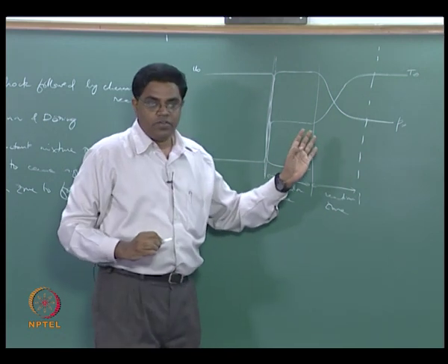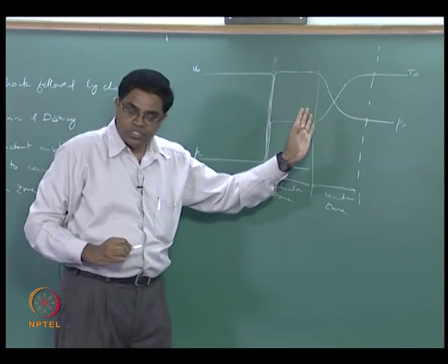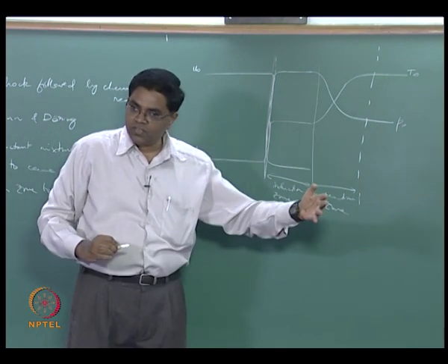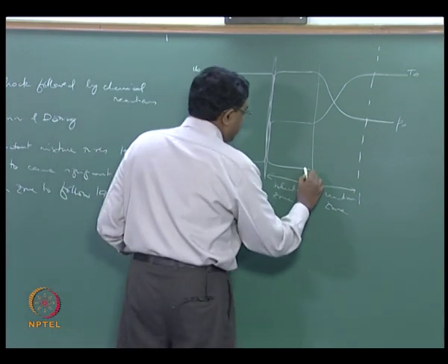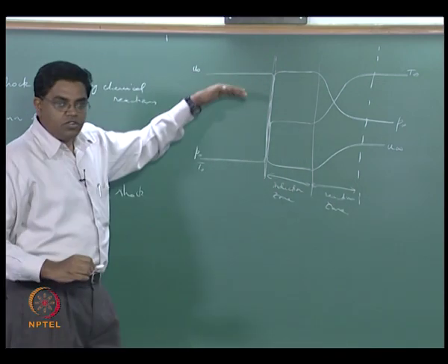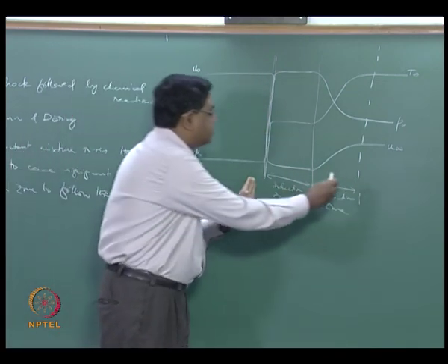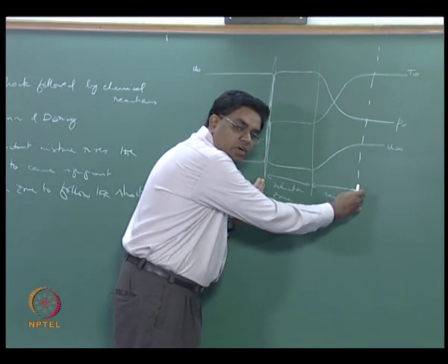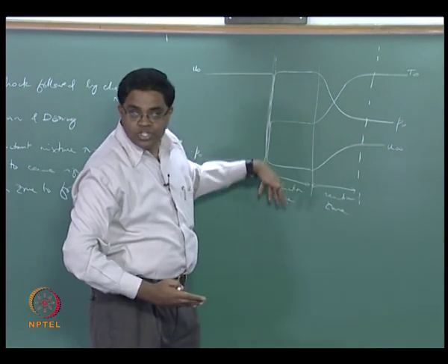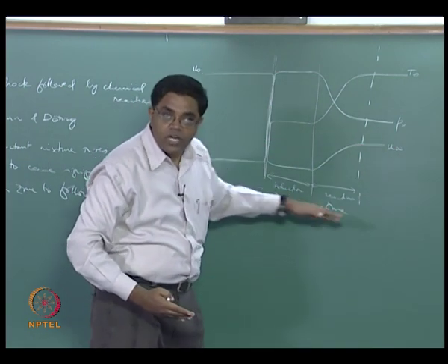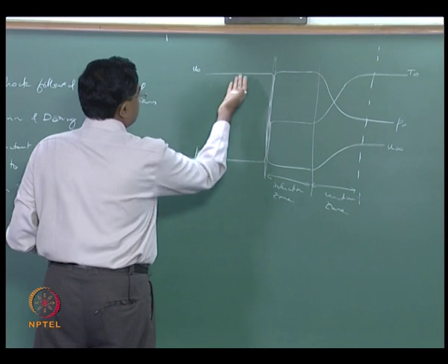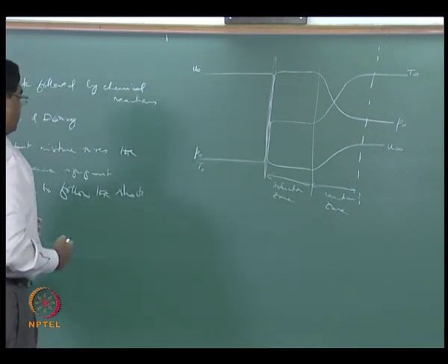And what happens when you have a flow going through a deflagration situation where you have a temperature rise? The density falls and therefore the velocity increases, right? So you now have a velocity increase that happens over here, so you get a u infinity. The velocity drop that you sense across the detonation wave in a Rankine-Hugoniot framework is actually this, but in reality if you go into the wave you find that the velocity drop is even further down before it restores to a level that is higher than here but lower than there. So these are the kinds of things that are going on, similar.